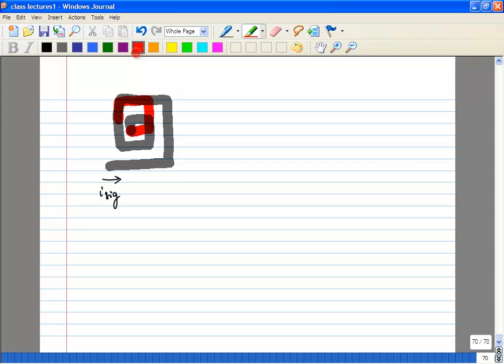You may do something like this, and you might be able to use multiple metal layers. What that means is, if the current flows through like this, it will start flowing through like this. So you try to maximize your overlap area. So this is the last kind of case we'll look at.